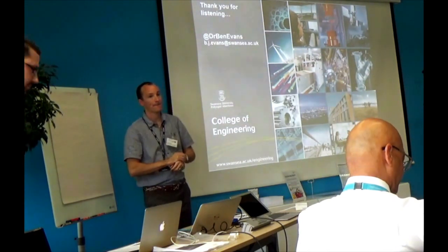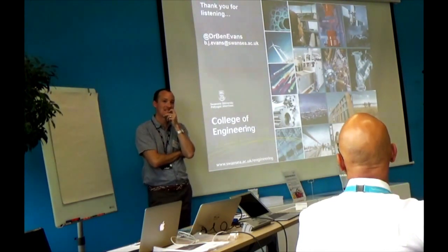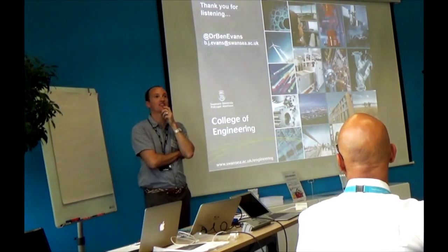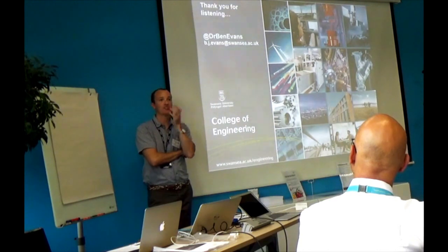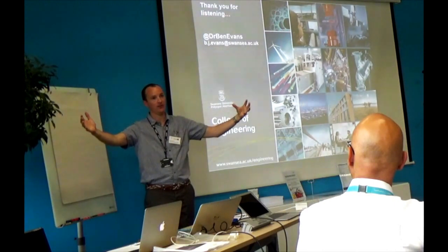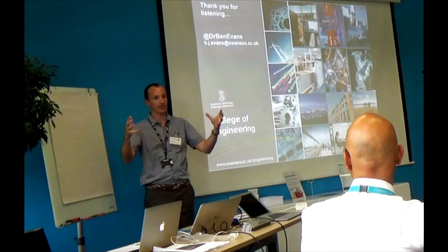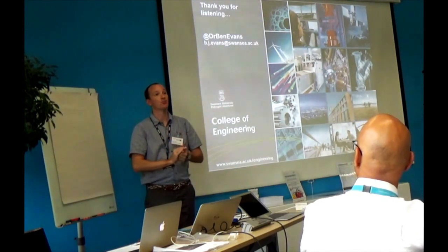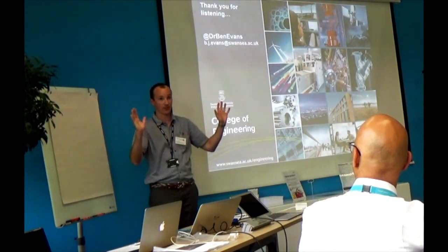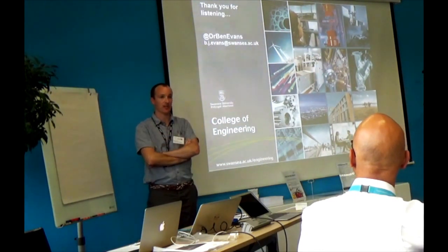In terms of the stability of the vehicle, are you fundamentally looking for areas of high pressure and areas of low pressure and the delta between the two? Is that what causes the instability? Essentially, it's the net loads and the way those forces are distributed across the vehicle that define your standard things, like static margins and so on, that define the vehicle stability. That's what we're working off at the moment. In terms of the actual dynamics of the vehicle, at the moment everything we run is static, assuming a static model. When vehicle dynamics is built into this, it becomes a whole lot more complex.